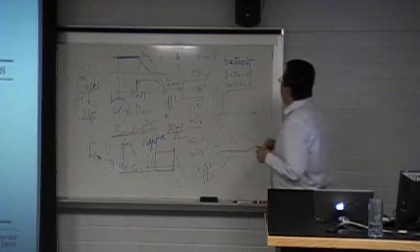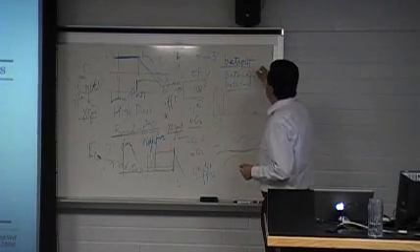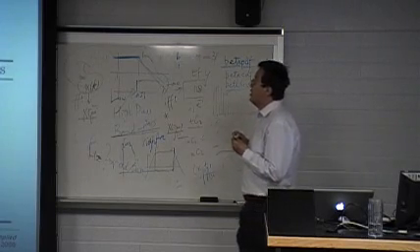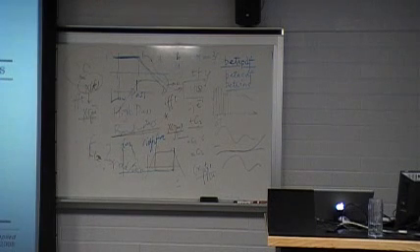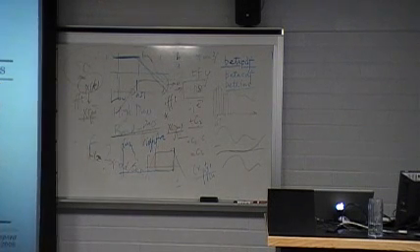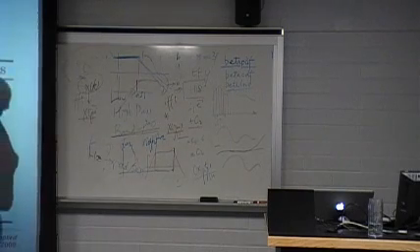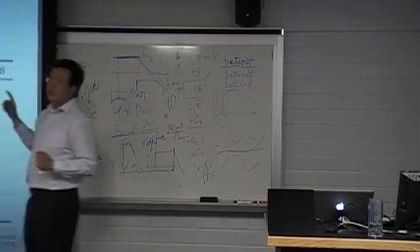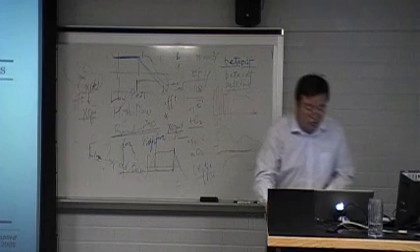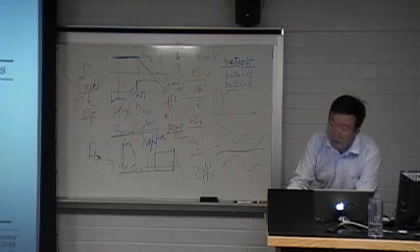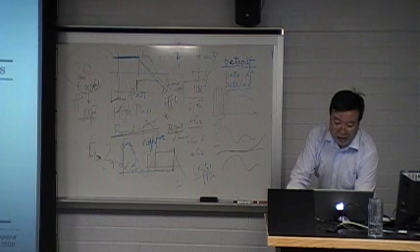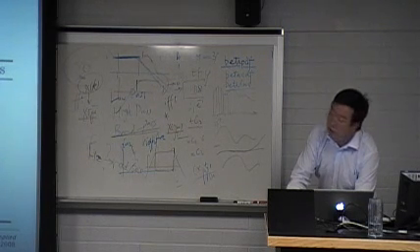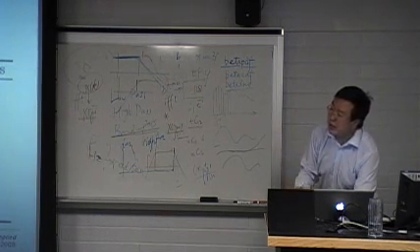And you can see that the function name consists of two parts. One is the name of distribution, the keywords. The other one could be PDF, CDF, INV, RND, stat, and fit. I will explain them by examples. PDF means probability density function. CDF means cumulative distribution function, as we explained the two concepts already.